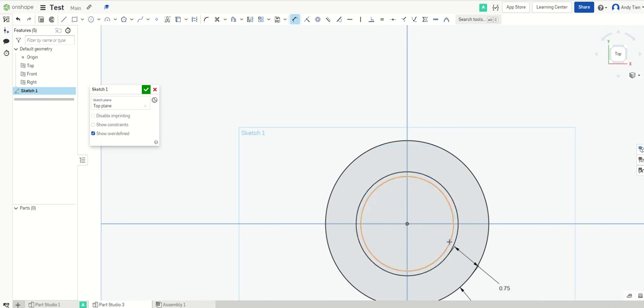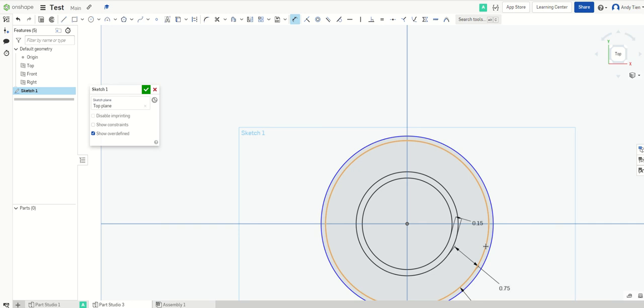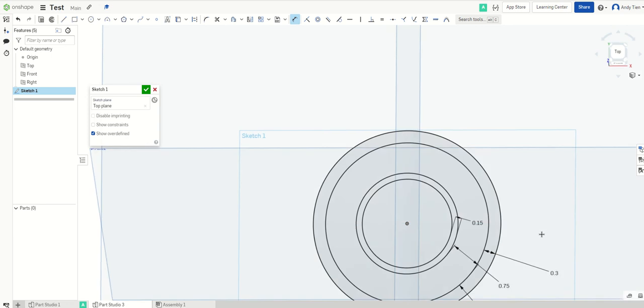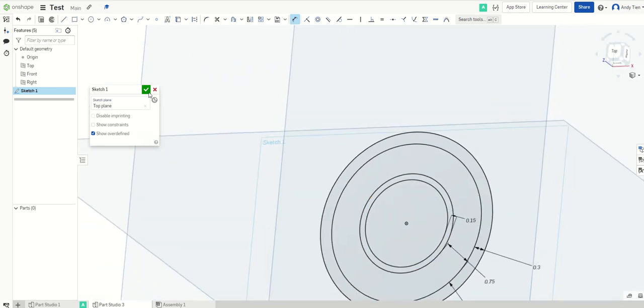So since it's a little plastic tab, it doesn't have to be that wide, because if it's very wide, you're gonna have trouble peeling it off, because it'll be more rigid. So I'm just gonna make it like 0.15 centimeters, and I'm gonna make this little thing 0.15 centimeters as well. Or actually, I'm going to make this 0.3 because it's the thicker outer wall. Bam, you got this. Okay.